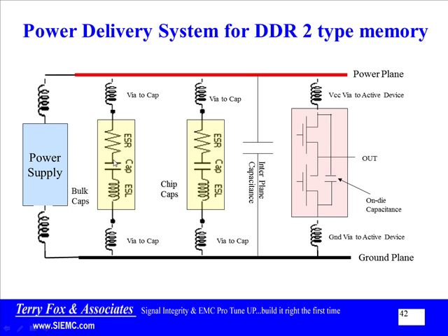These guys are going to be your 100 microfarad sort of capacitors. But as capacitors, you'll find that they've got equivalent series resistance internally. They've got the capacitance which you wanted, but they've also got equivalent series inductance internally. There's also the mounting impedance to the plane on the power side and the mounting impedance to the plane on the ground side. So consequently, these can have fairly significant inductance associated with the 100 microfarads or 300 microfarads or 47 microfarads or whatever these things happen to be. But these are connected to the power and ground plane.